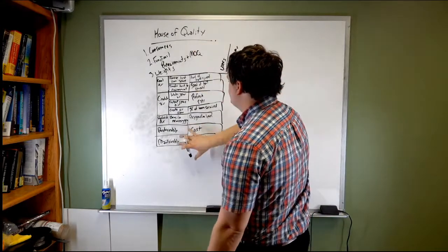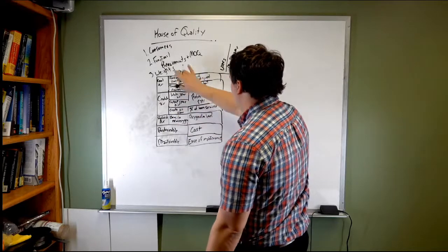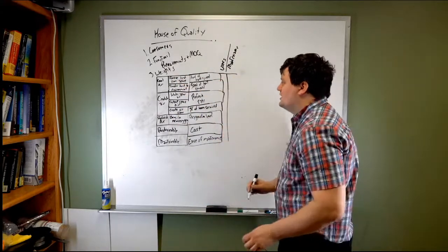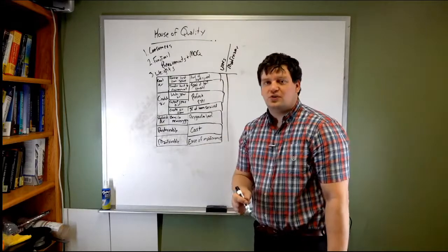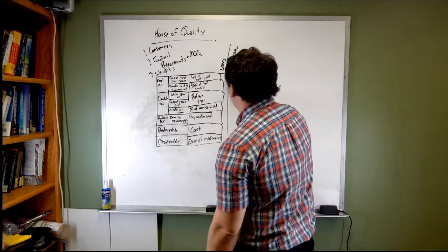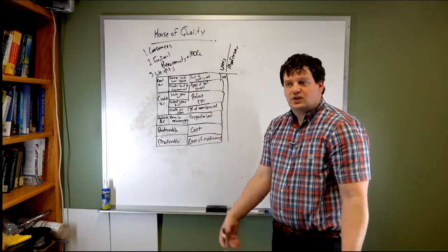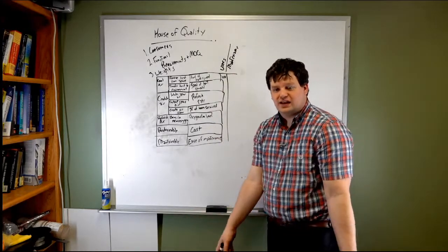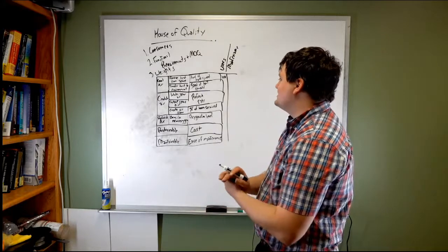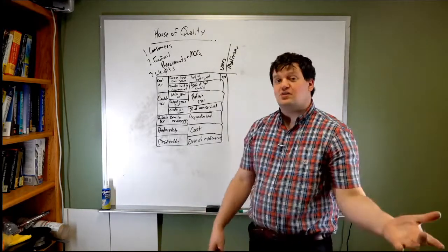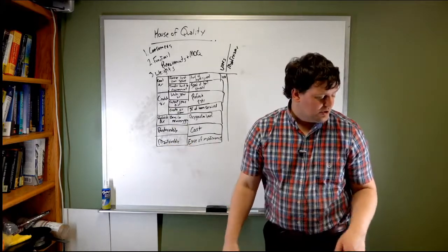2, functional requirements, measures of quality and constraints. 3, we're gonna put together the weights. So how important is it to a user, the amount of heat removed? Well, that's probably a 10. In fact, we don't even care about how fast it goes. We care about most, like how much heat does this produce? Usually your weight, what you do is you scale it on a scale of 1 to 10. What is the most important?